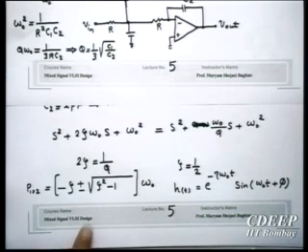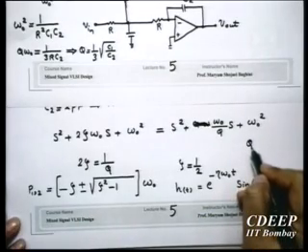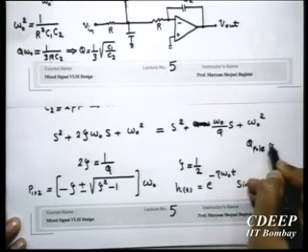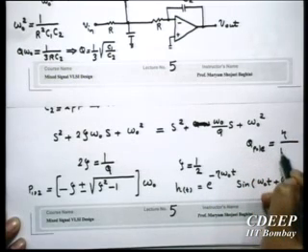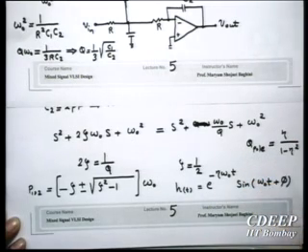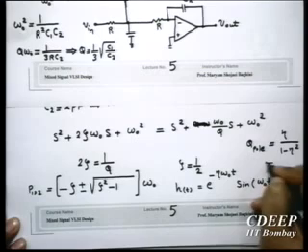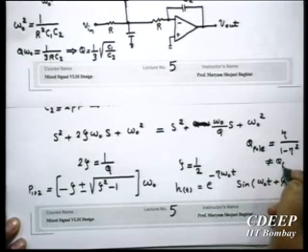If you look at Q of pole, it will be root of 1 minus zeta square upon zeta. But Q of filter is not always equal to Q of pole, because Q of filter is equal to 1 upon 2 zeta.